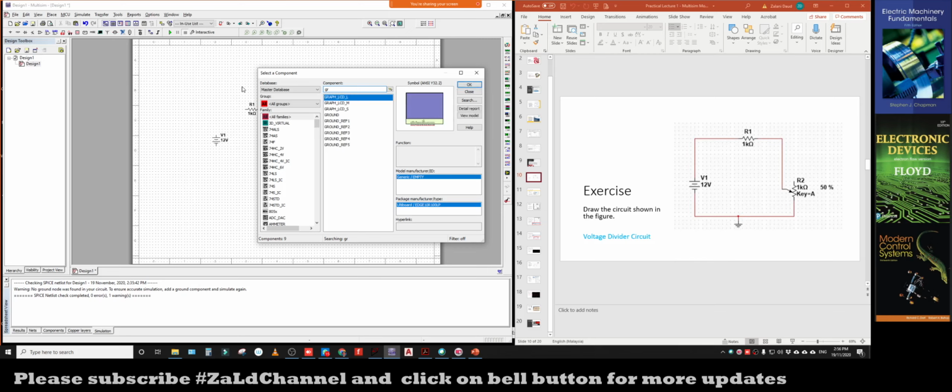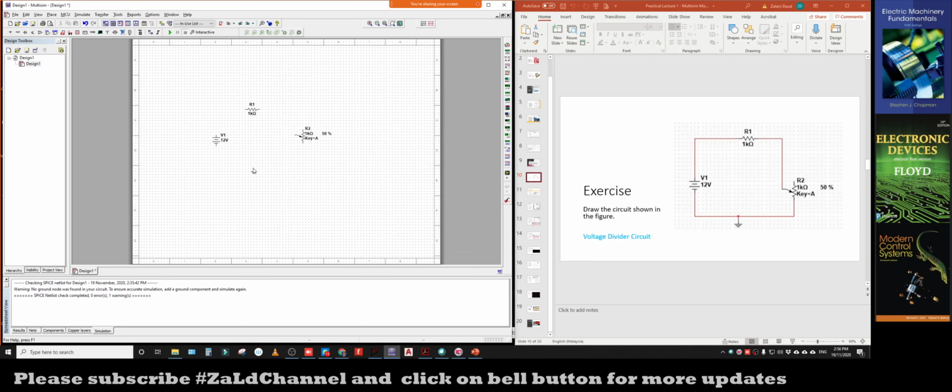Okay, so you can just specify this group as all groups. If you don't know which group a component belongs to, you can just select all groups here, and then search in the component search bar, for example grounding, GRO, then it will appear as ground, and you can select this. So now place the ground somewhere here.